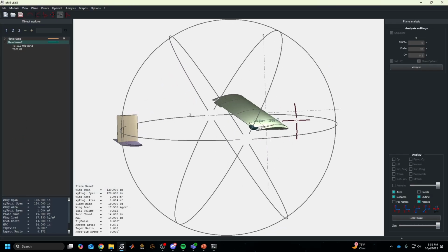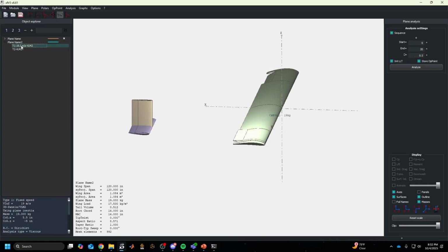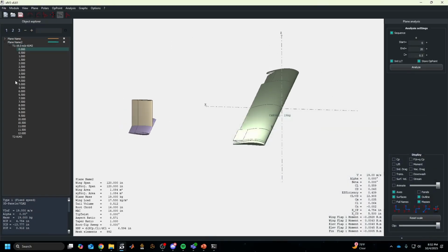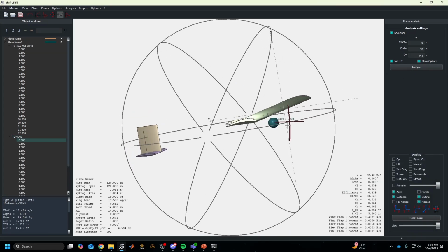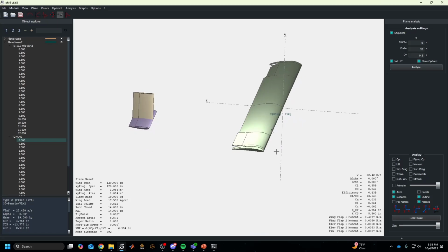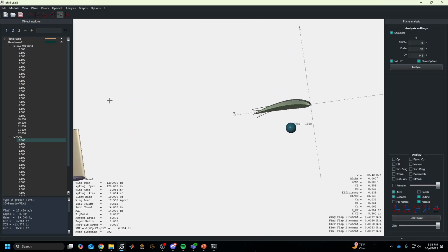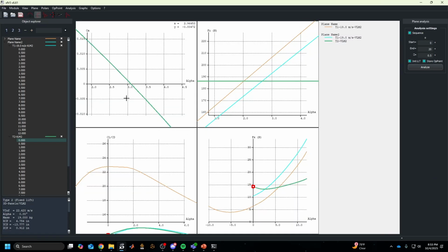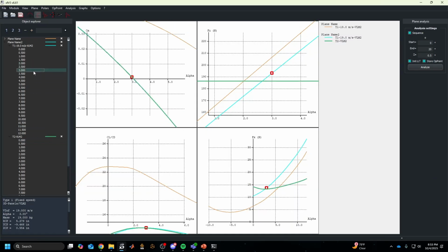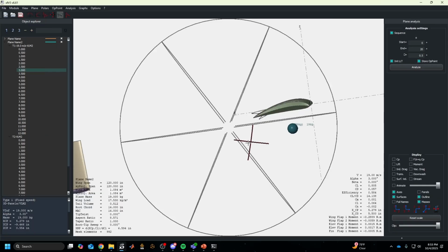And then we're going to define that, and just for fun, let's try and analyze this. Theoretically, our pitch should be the same, right? Because in terms of the longitudinal direction, these are going to cancel each other out, because one's up and one's down in the same x position, right? You can kind of see that it's symmetric longitudinally. But let's go ahead and see if that's true. Not really. It did actually shift it, right? But still, our trim alpha is pretty good. That's not bad.